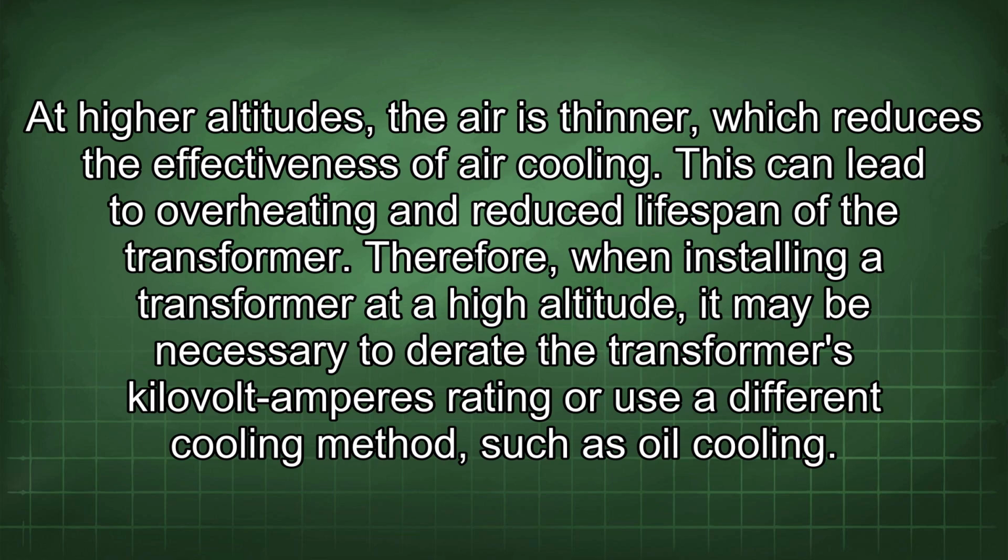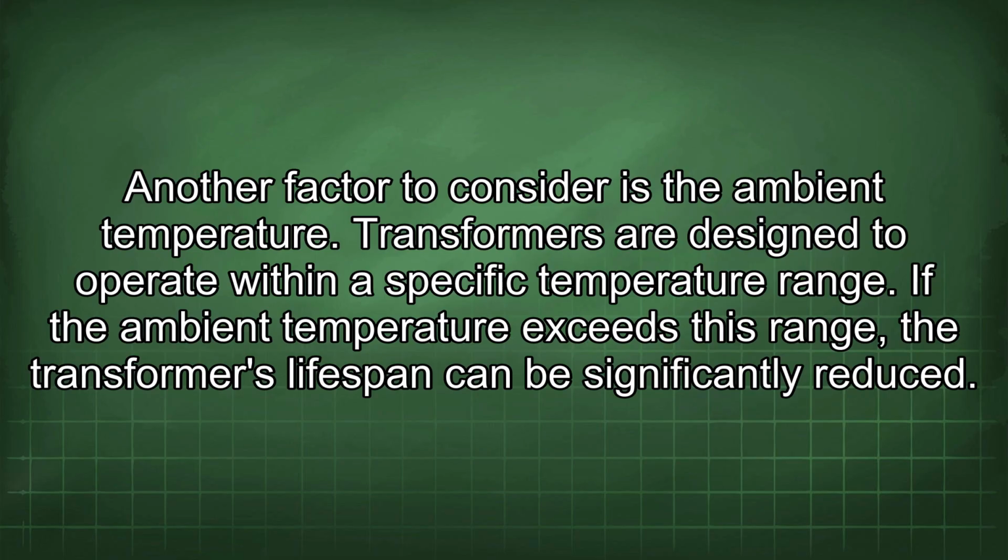Therefore, when installing a transformer at a high altitude, it may be necessary to derate the transformer's kilovolt-amperes rating or use a different cooling method, such as oil cooling. Another factor to consider is the ambient temperature.